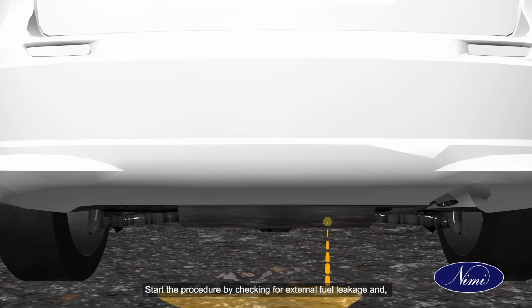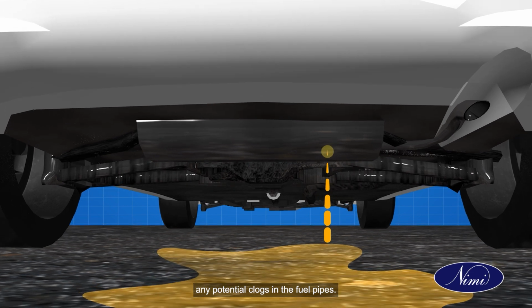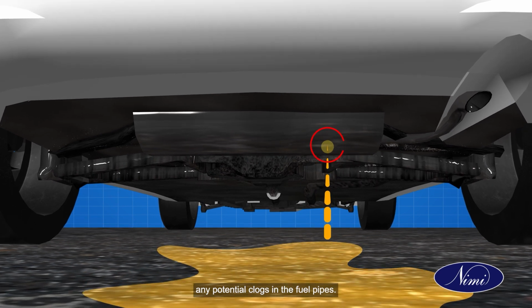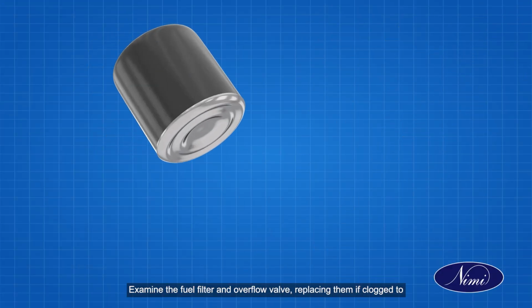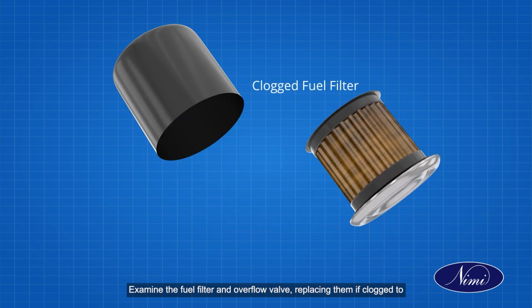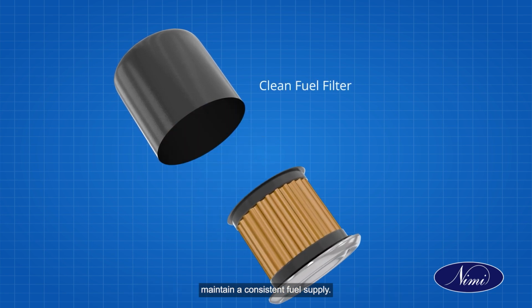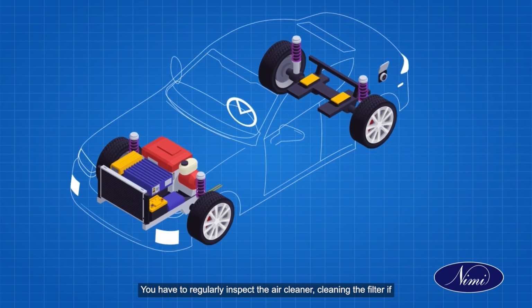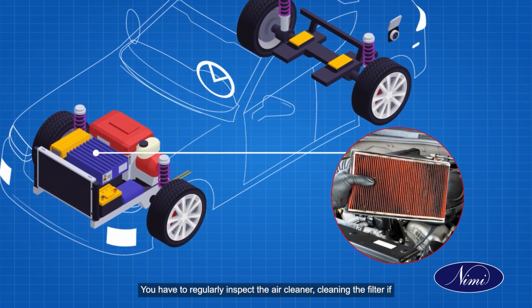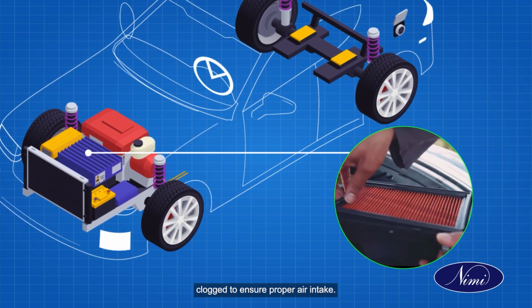Start the procedure by checking for external fuel leakage and any potential clogs in the fuel pipes, promptly addressing and rectifying any issues found. Examine the fuel filter and overflow valve, replacing them if clogged to maintain a consistent fuel supply. You have to regularly inspect the air cleaner, cleaning the filter if clogged to ensure proper air intake.